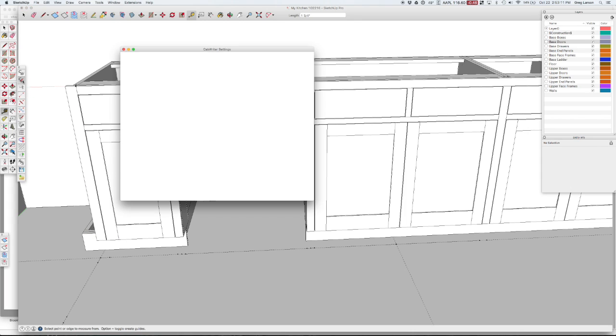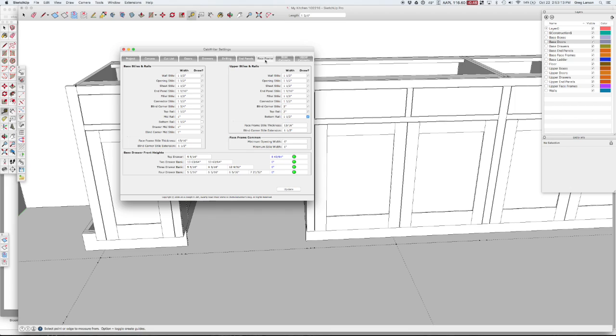If we go look in our face frame specifications, a butt style is, where's the butt style? Right now, it is the same as the blind corner style. It applies to both the butt and the blind. We're going to break that out later into two separate settings, but for right now, this is what specifies what happens in the corner.